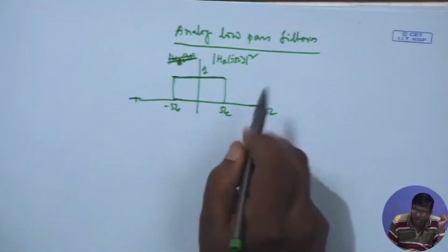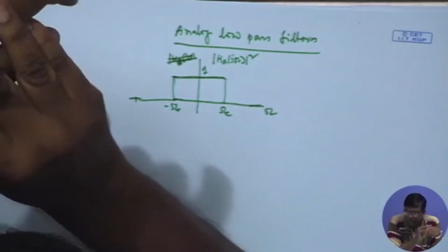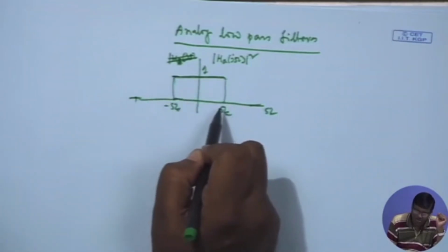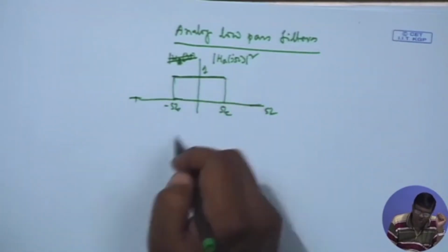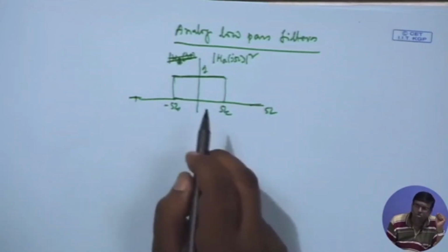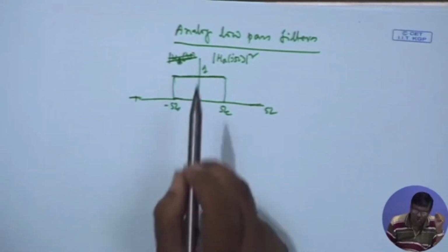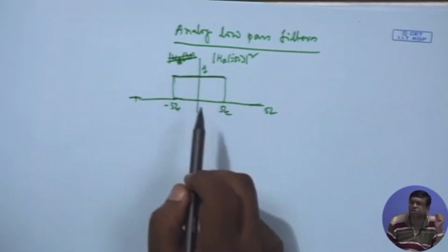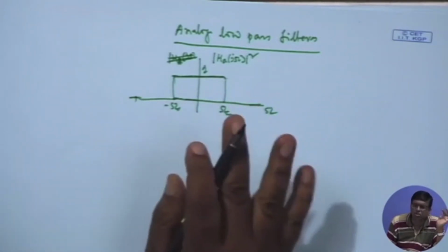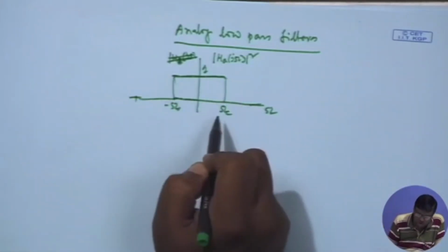Okay. Normally, the transfer function is given both by magnitude and phase. If it is ideal, the magnitude should be flat within the desired pass band of the filter, and the phase response should be linear in omega, but you cannot design to satisfy both. So, what we do is concentrate on satisfying the magnitude response as much as possible, and then we hope that the phase within this band is somewhat close to being linear, not very widely off linear. So, we will concentrate on this.